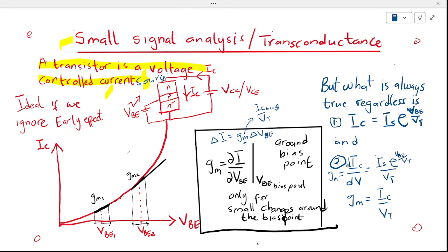So that means that you have this current IC being drawn from VC here, the power supply here, but then it's being controlled by another voltage, not necessarily, even though VC is the one supplying it. So if I change the value of VC, if only VC is capable of producing the current, it shouldn't change. That would be an ideal current source.